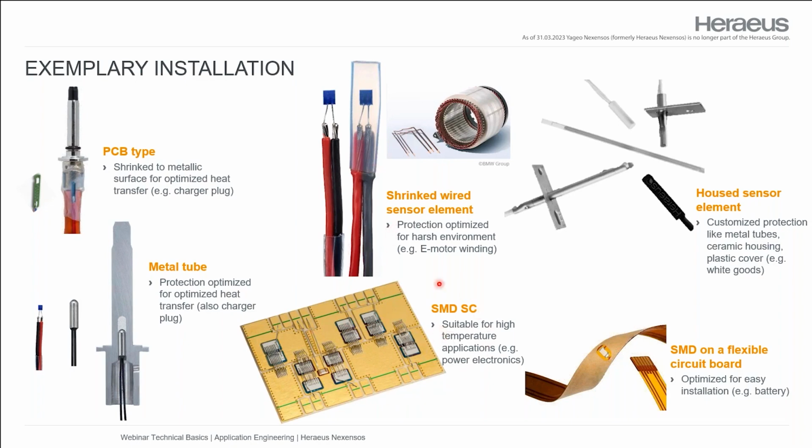This is the application you see here with that golden shiny PCB for our sinterable SMD, which is called the SC, as in sinter chip. And the position is here very central, in the middle of 4 power dies. In that situation, these dies are IGBTs. And the better this power module is working, the higher is the frequency of the switches in that IGBT module, and higher frequency leads to higher temperatures.